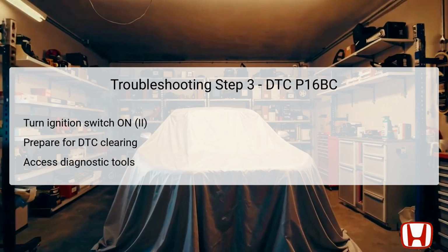For the third step, turning the ignition switch to the on position 2 is necessary. This action powers the vehicle's electrical systems without starting the engine, allowing the use of diagnostic tools. It's essential to have the Honda Diagnostic System, HDS, ready at this point, as it will be necessary for clearing previously recorded DTCs.